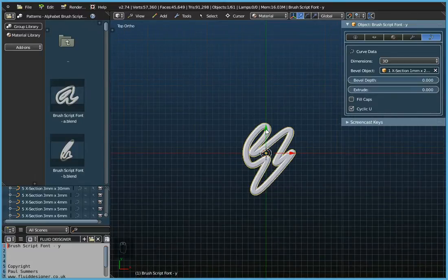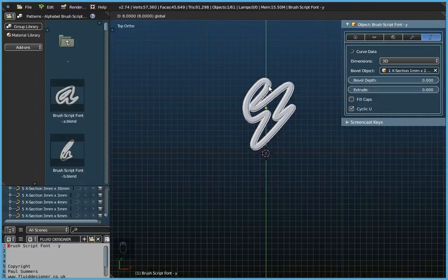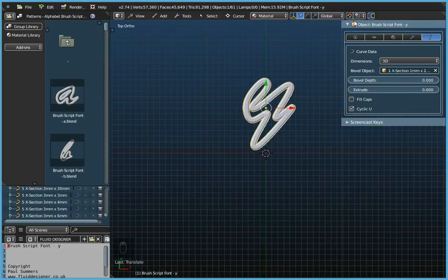And if I point at the green arrow at the top there, I'm just going to move it slightly away from the center. Now notice it's jumping up in 1mm increments, and the reason for that is because this feature here called snap is automatically switched on for you, and that's quite a useful feature, the snap.